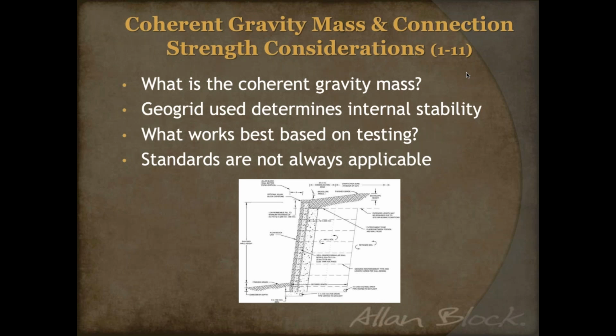Now, of course, I said standard wall there, because if there are any special considerations like a surcharge above, any slopes, anything like that, or a tall wall, your wall might require longer geogrids or more buried block or certain things like that where they go beyond the standard. We've done all of the testing to see what works best, but that doesn't mean that it works for every situation.